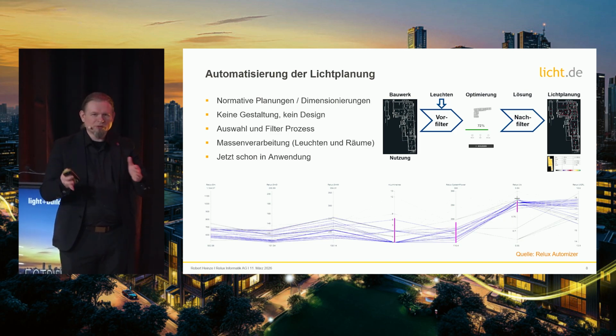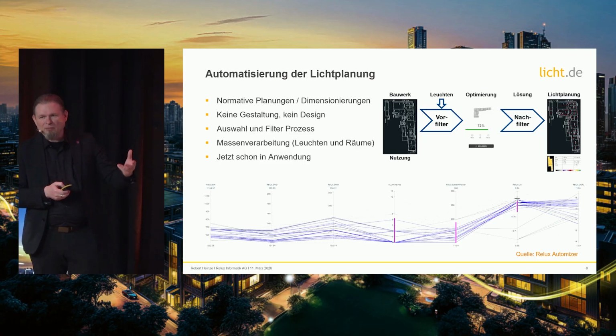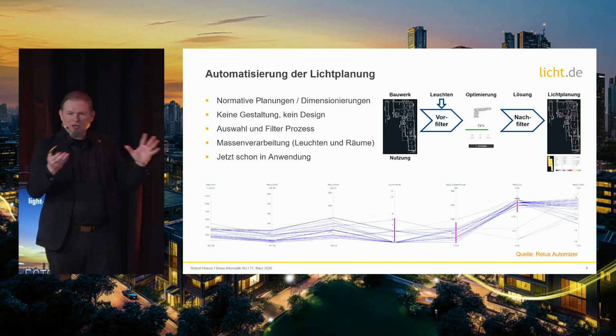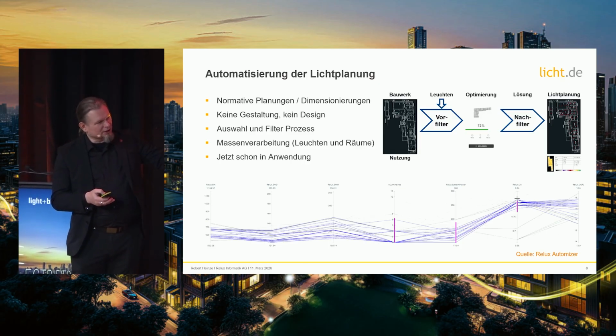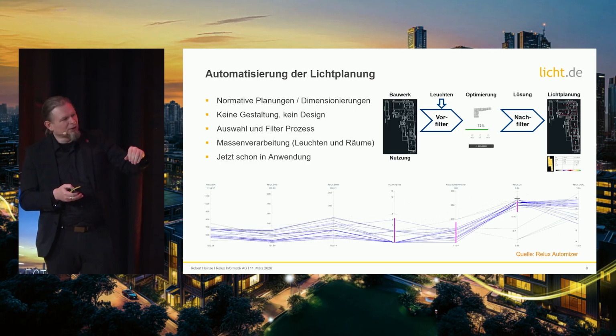So these 20 luminaires are good for an office. These other 20 ones are good for a corridor. And then you allocate a luminaire to each room, and also you compute the right location in order to fulfill 12464, and then you get a group of results at the bottom.